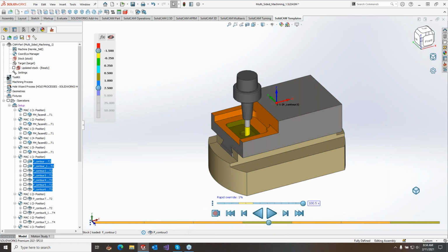I don't have a part set up now for this, but if you are playing in machine time playback and you are playing a heavy toolpath that the CPU cannot keep up with the real cycle time of the machine, this happens especially with 5-axis toolpath. It is very possible you have a 5-axis swarf cut at the machine that might only take, let's say, 10 seconds to do along a tapered wall.